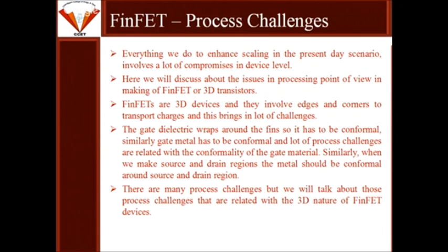Okay. So everything we do to enhance scaling in the present day scenario involves a lot of compromises at the device level. Here we will discuss the issues from a processing point of view in making a FinFET or 3D transistors. FinFET or 3D devices involve edges and corners to transport charges, and this brings a lot of challenges.